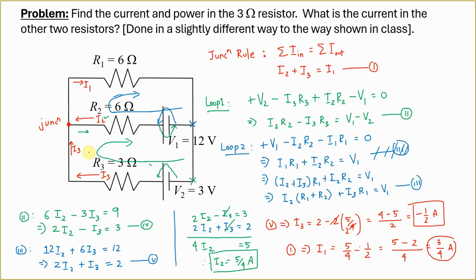Yes, yeah, so ultimately the math works out in a way that your junction rule is still satisfied. So it will basically be a summation of the fact that the current going in must be equal to the current going out. So here what we have done is that I2 goes in, I3 goes in, and I1 comes out. Actually, in actuality what happens is I2 comes in, I1 and I3 both go out. That is how the math works out.